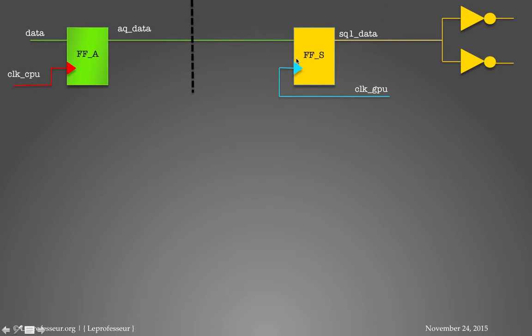So we have to enforce that requirement. Let's say, for example, this is my clock. This is the clock edge, the rising edge. Every flip-flop has a requirement that your data signal should be stable before the rising edge of the clock.